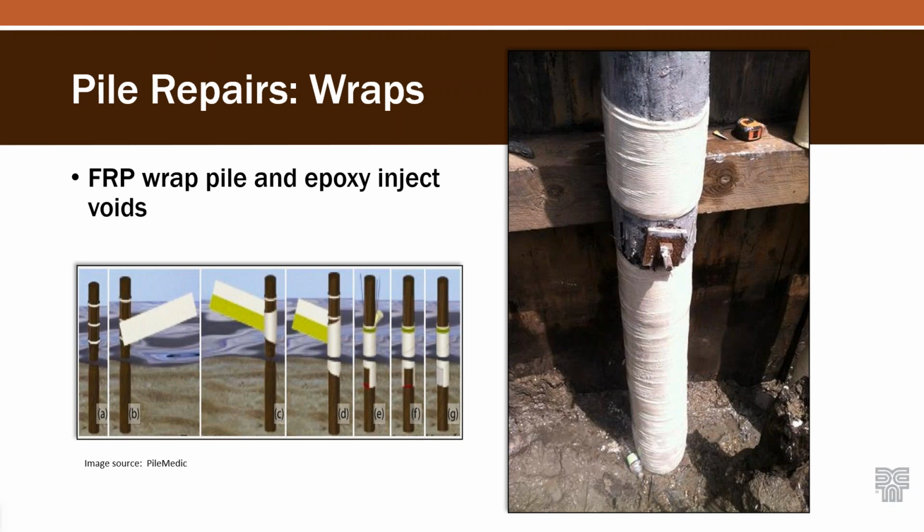Some of the benefits of this kind of repair is that the original pile stays in place, right? So there shouldn't be any need for shoring as you do this repair. You're not cutting anything out and changing the structural path. The image on the left, and I'll give the reference to Pile Medic on that one, is showing it being installed underwater. And so you might be able to install these in water. There's lots of flexibility. It's not a preferred repair method for me, just because of the crews I've worked with, it wasn't their preferred method.